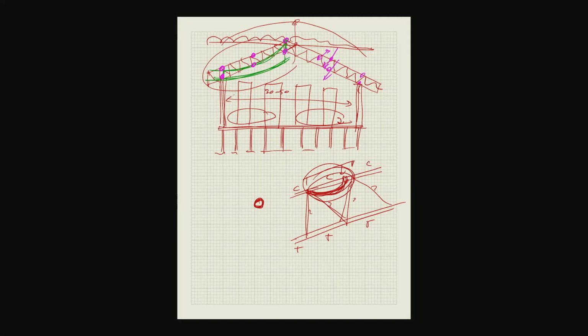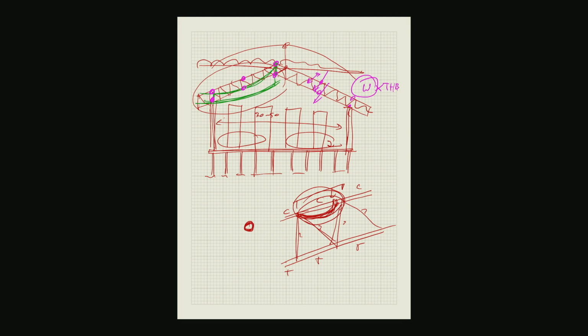And the roof truss is actually an important component of the cost of the factory. As it is steel, and erection is needed, right? So the fabrication is expensive already, plus the erection, painting work, and so on and so forth. The steel cost is weight multiplied by unit cost. So the paint comes along with the weight. The material and the fabrication just come along with the weight. So generally, structural engineers try to minimize the cost or the weight of the roof truss in the design. And the point is that when the value engineering effort on the roof truss is too much, then you might be at great risk in the structure. So just be very careful.